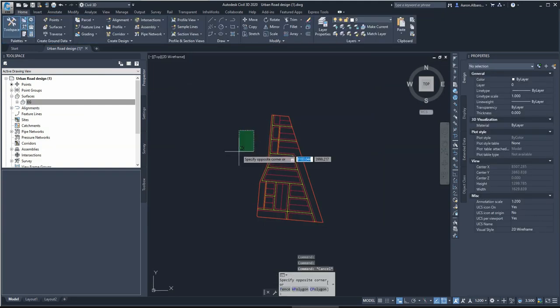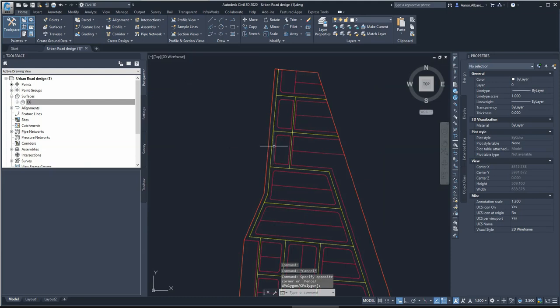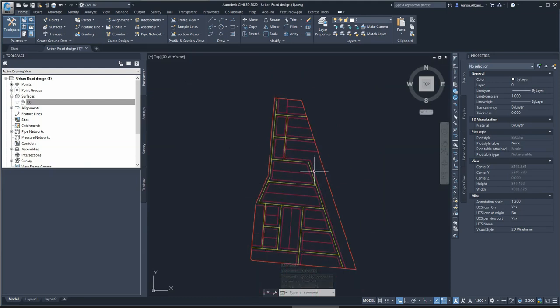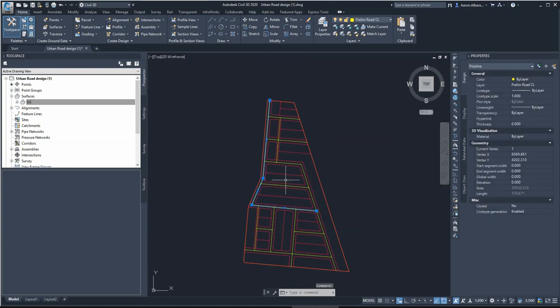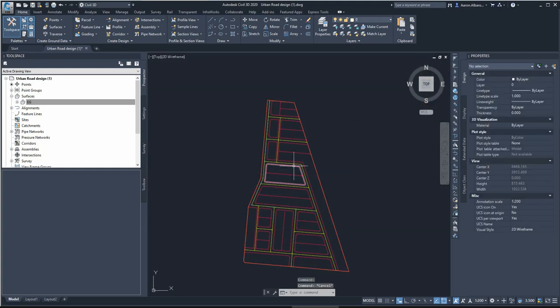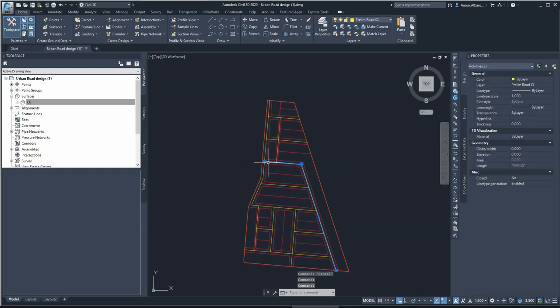My plan is, and this is just for the practice side of things, we've got all these yellow lines representing the center line of the proposed roads. Obviously the center line without adding any curves or actual road design. So this is what we'll be doing in this stage. I'll be designing this road here as alignment 1. I'll choose this road to travel from north all the way to south, as well as I'll design this road here, and I'll call it alignment 2, again traveling from this point here north to south.